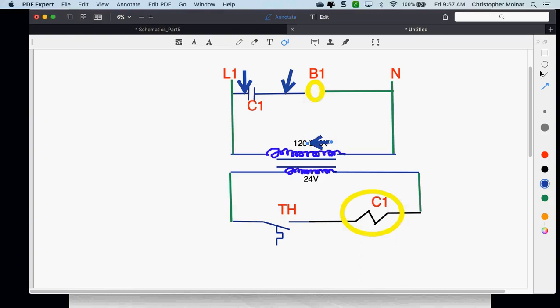Okay, I close this thermostat. In other words, I adjust the set point on a thermostat to make it close. I energize this relay coil in the process, and if I have 120 volts here, what's my problem? Thermostat's closed, coil's energized, I have 120 volts between that point. What's my problem? The coil's done. Something's failed because it's not closing the contact. That relay has to be replaced. You're not going to fix these.